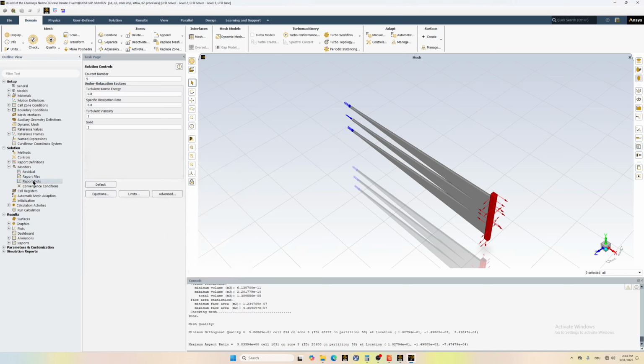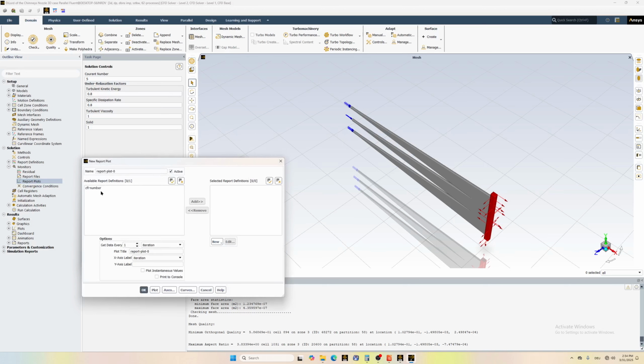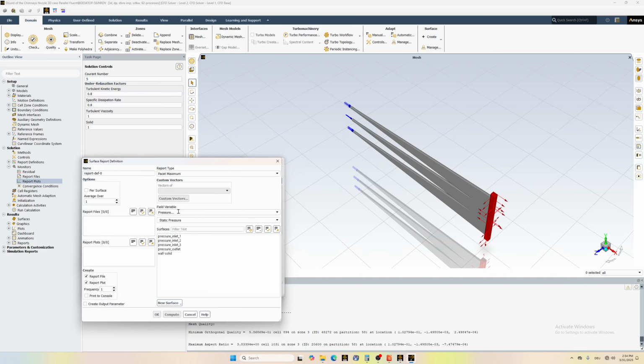Okay. Now I like to monitor the density at the outlet. It's my way to run the simulations. You can monitor anything else. It doesn't matter as long as you monitor one of the parameters, so that it doesn't change anymore in time.